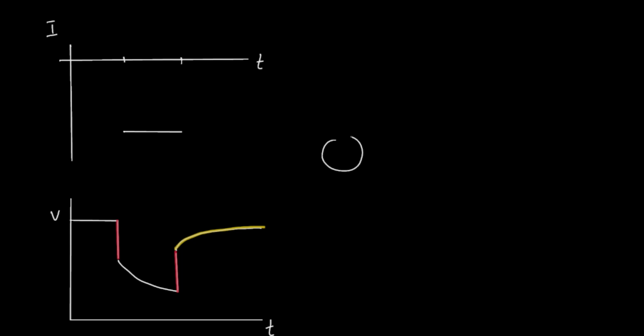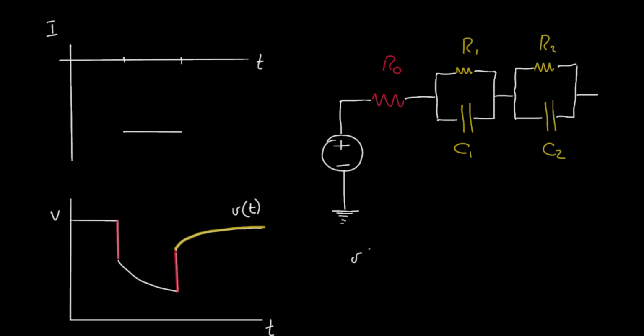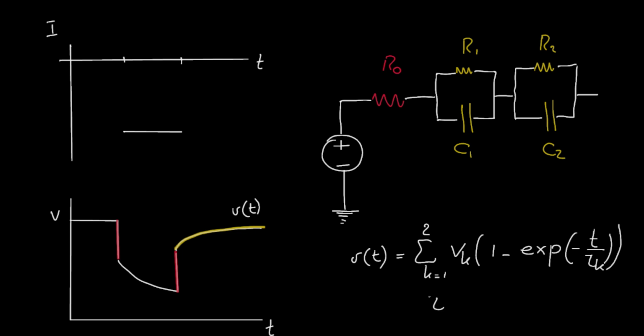This is why it makes sense to model a battery using an equivalent circuit with a voltage source, a series resistor, and a set of RC pairs. The first one takes care of the voltage at open circuit. The second one models the ohmic drop. And the RC pairs have a response that can be written as a sum of exponentials, each of them with a time constant given by R times C. So, the goal is to fit the response of the equivalent circuit to the measured voltage.